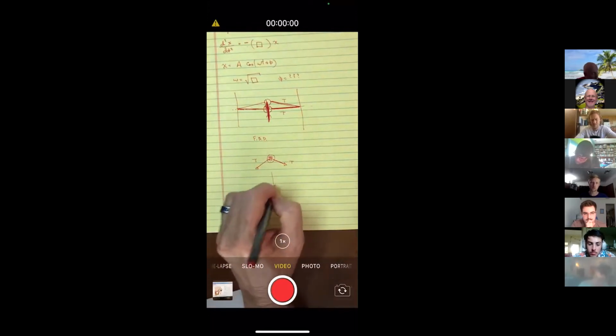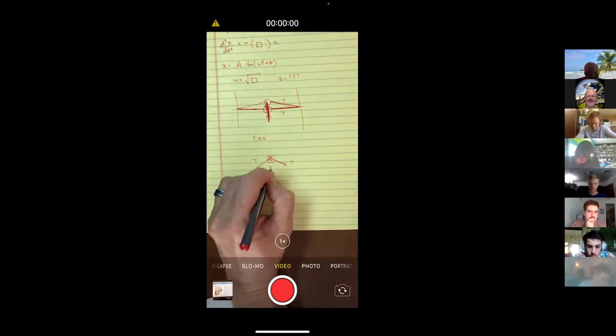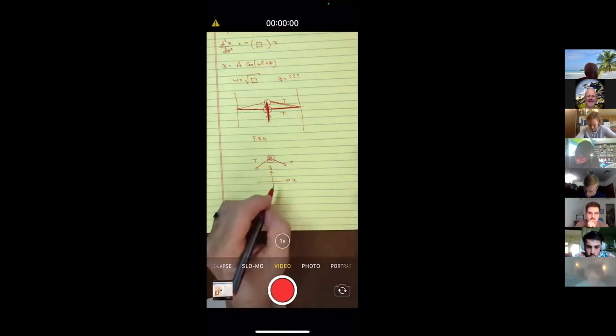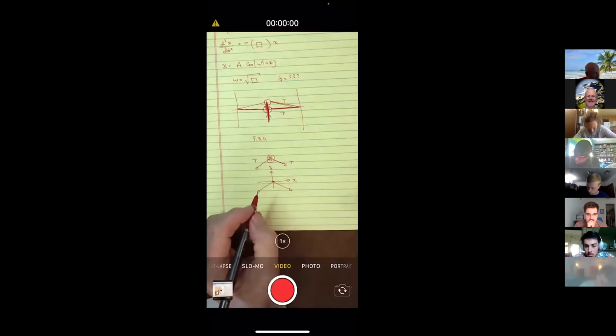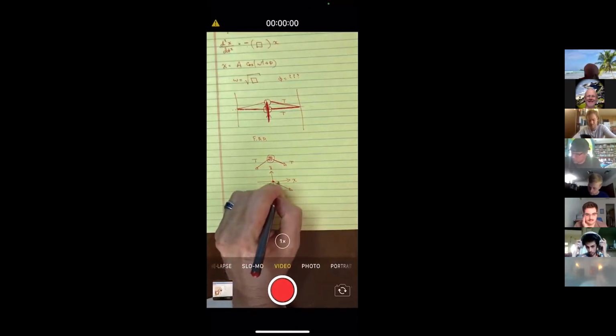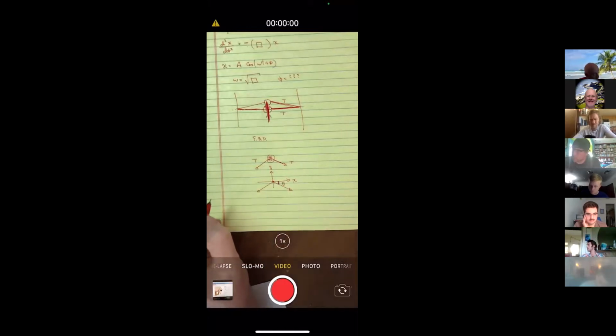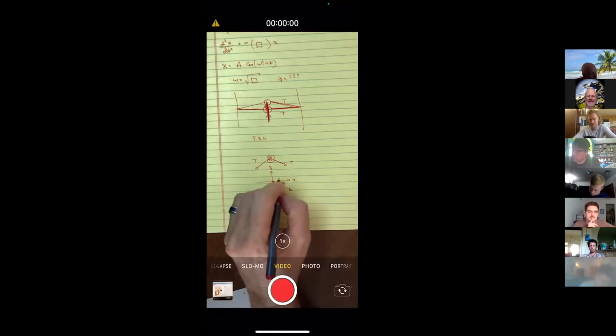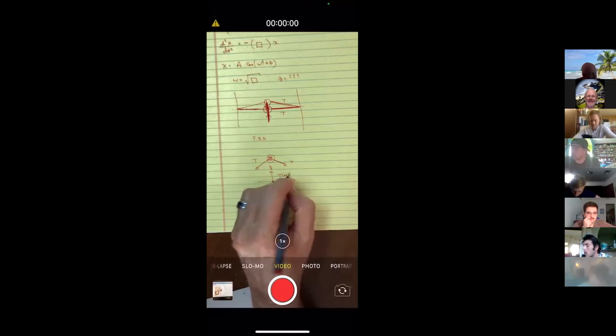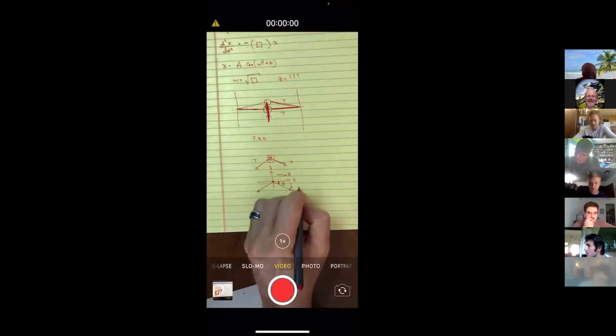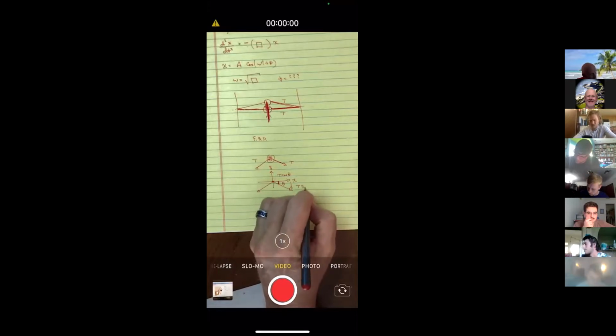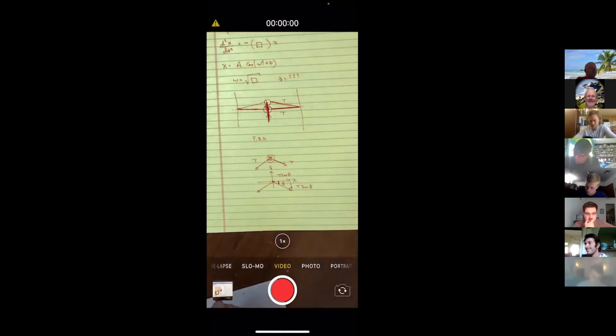So then if I make a grid, calling this the y-axis and the x-axis, so kind of the traditional grid, and I've got a tension this way and a tension this way. If I were to call maybe this small angle here theta, then the x component would be the tension times cosine of theta. And the vertical component would be the tension times the sine of theta.